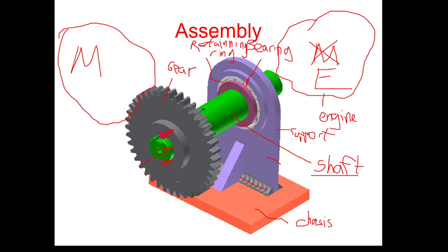For standard objects, there is no need to create or draw detailed drawings, because, thanks to the publications of the standardization associations, we have the documents for standard objects in the libraries, and someone can gather full information about a standard component. But if the component is a non-standard one, this means there is no such document for that object, then yes, a detailed drawing is needed to be able to inform the reader of the shape and size of the object.